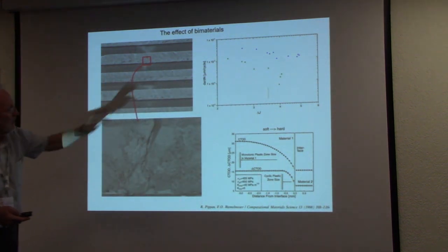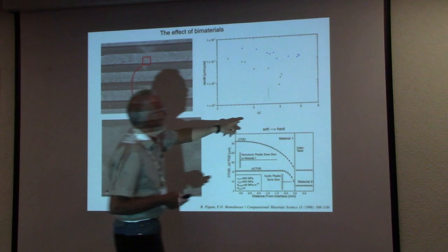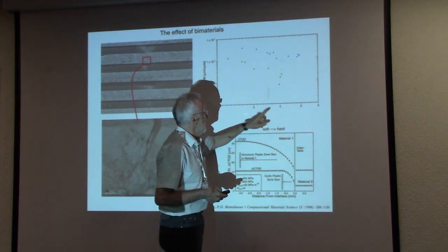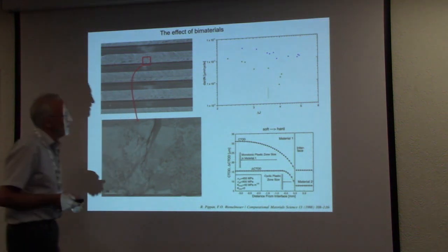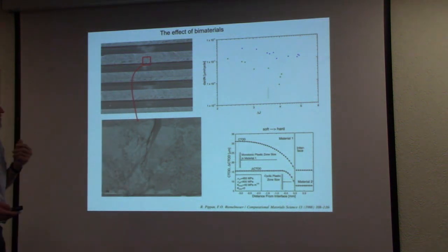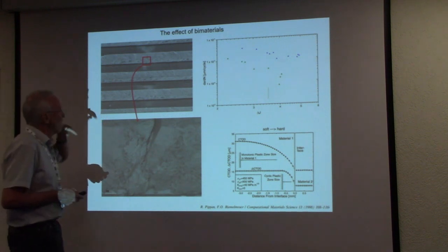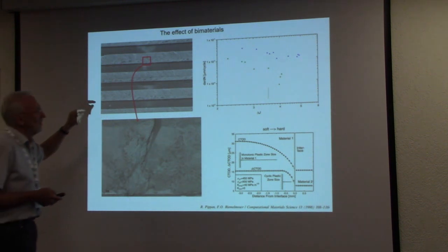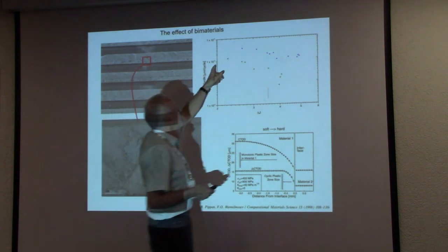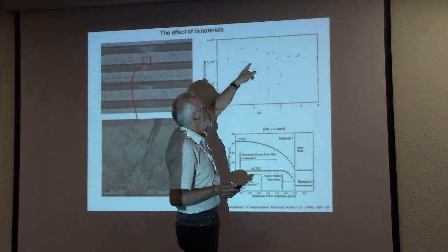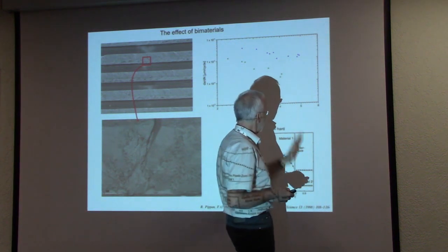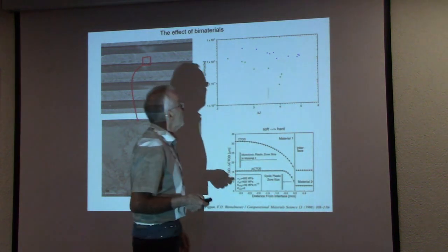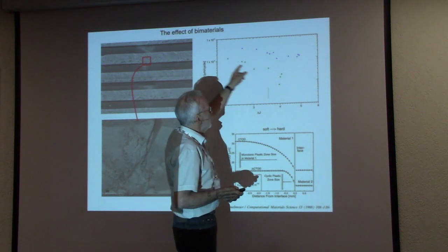Here the crack length is not plotted, but in principle this is equal to the crack length times the applied strain and the yield stress of the material. Here different materials are plotted. Interesting is that when the crack length increases here from the surface and runs to approximately the end of the metal film, the crack growth rate decreases.